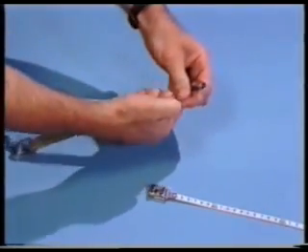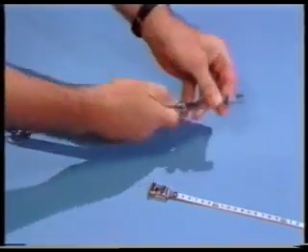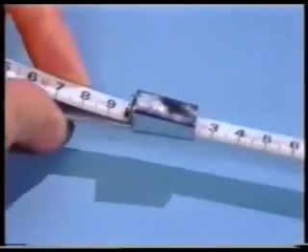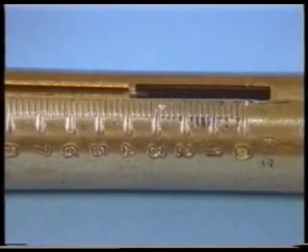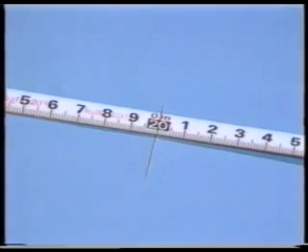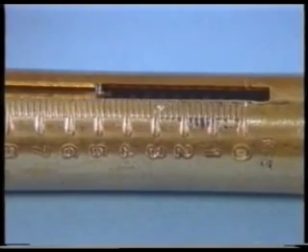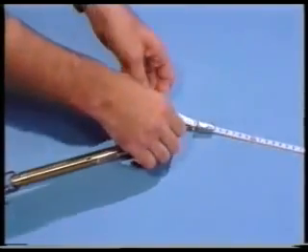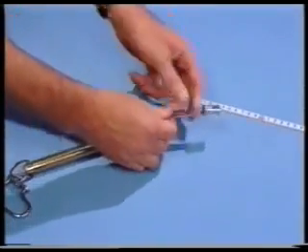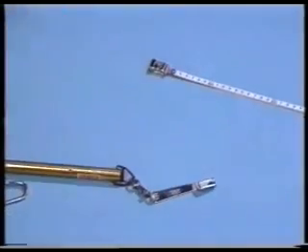Tension can be applied to a steel tape using a spring balance hooked into a roller grip which clamps onto one end of the tape while the other end of the tape is held firmly. The spring balance is pulled until the required tension is registered on its sliding index. If the tape is pulled at any other value than its standard tension, then its length will be different and a correction will be necessary.